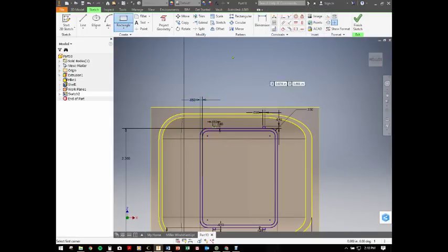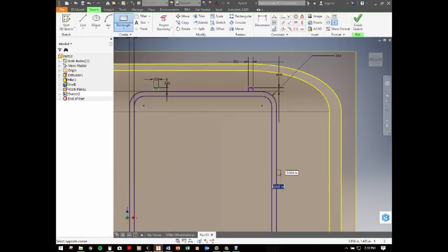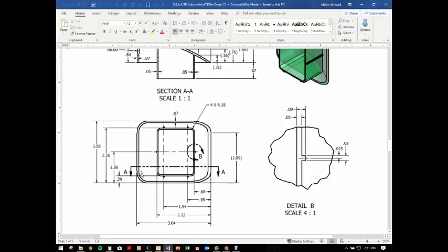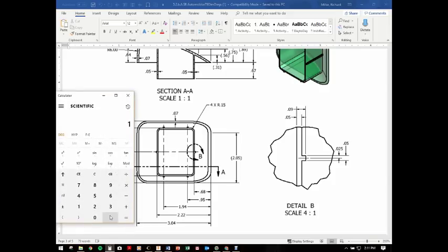Next thing I need to do is the front ones. Again, the front ones are centered up in here. We're just going to go ahead and place a rectangle. This time I do the 0.04 first because it sticks out 0.04 and it's 0.05 thick. And I'm going up, using this one, 1.28 minus 0.025 is 1.255.